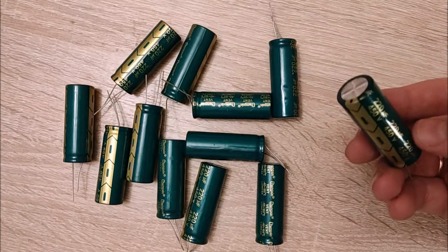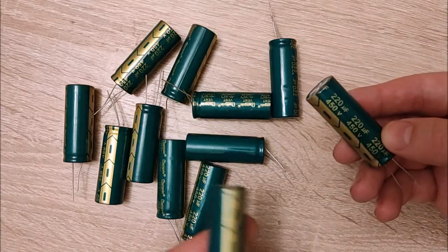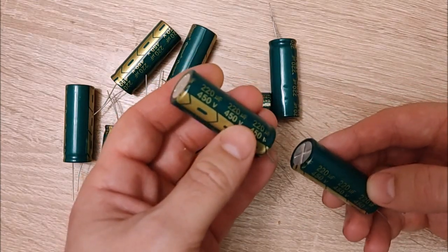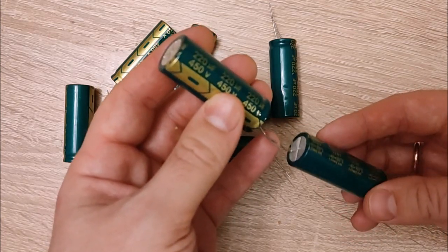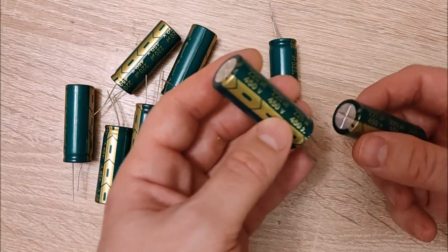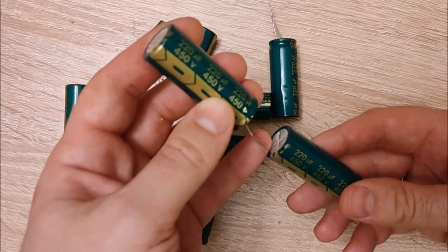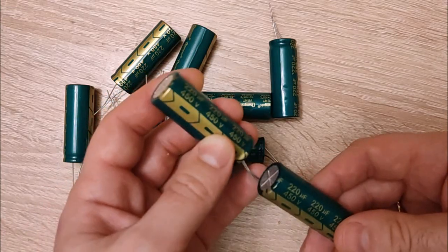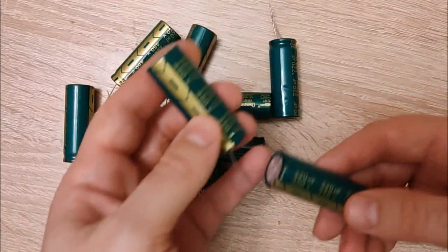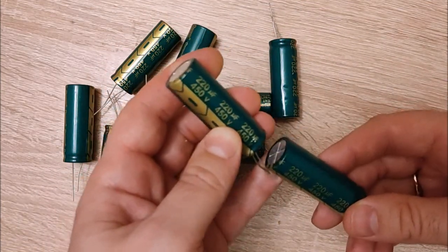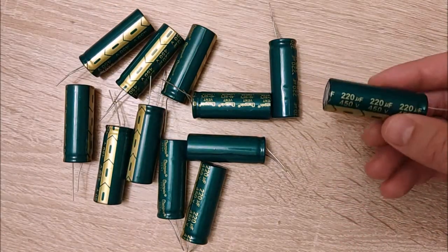So, if I want to increase voltage more than 450 volts, I need to connect such banks in series. Two connected capacitors of 450 volts give us 900 volts, and accordingly we should have some charging circuit for each stage of such cascades of capacitors for a multi-stage accelerator. Let's look how we can get it.